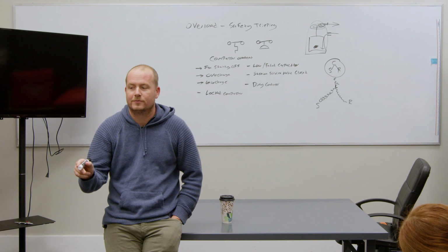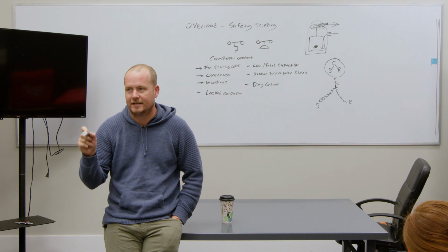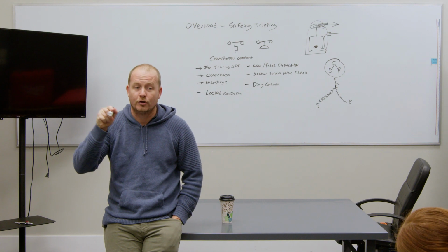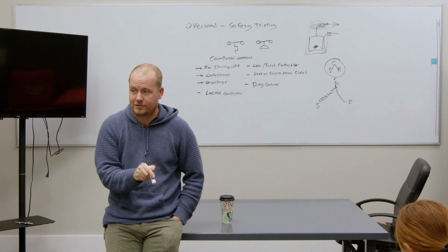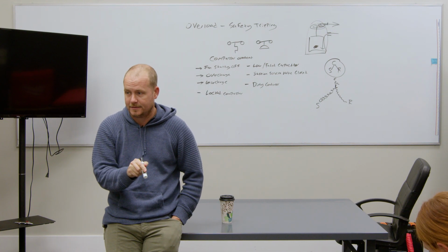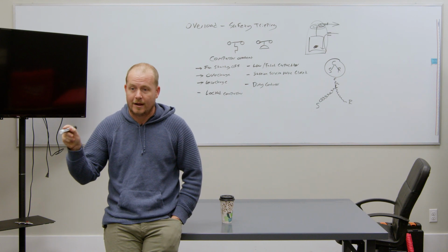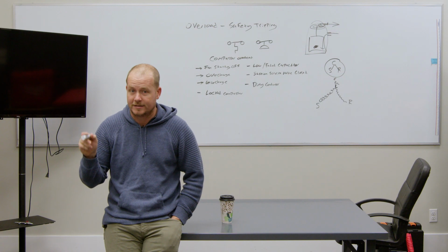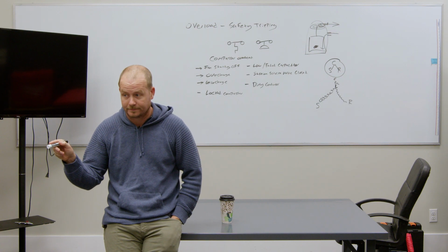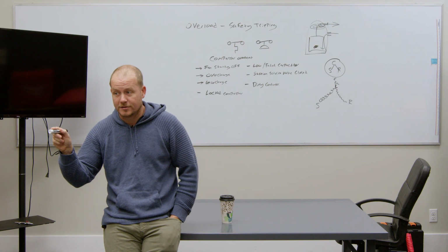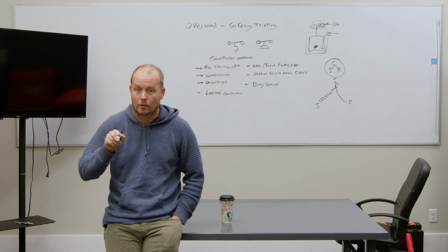Yeah, and that's what I'm suggesting: do I think there can be a case where a system could be frozen and you show up and the compressor's out on thermal overload? Yes, because mass flow is a big factor in keeping a compressor cool. But I think it's very unlikely on a typical system that has a proper charge and a frozen evaporator coil and a normal length line set.